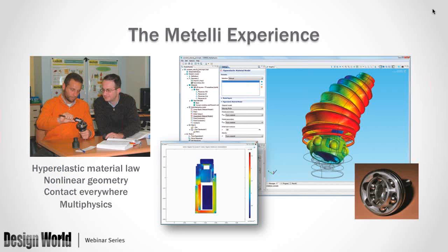It's interesting because you have these spheres that are touching the casing on the outside. There's a lot of contact going on. There's also a hyperelastic material model. That's the boot seal that you see stretching out there. And obviously there's going to be nonlinear geometry as that boot seal is moved. As I mentioned, there's contact everywhere, and there's also multiphysics here. With this kind of coupling, you actually include all the different nonlinear effects in one and the same model.